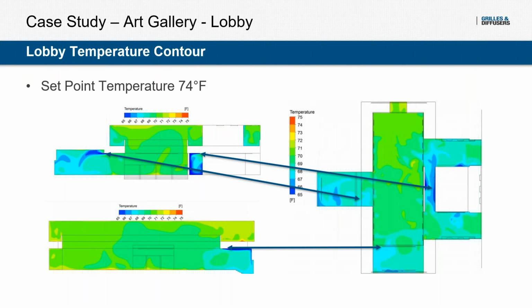That means, or we're assuming, that the supply air system is oversized for the assumed loads. So this is something where we can minimize the supply air system. We could reduce the temperature differential because the loads were not as large as we thought they would be.